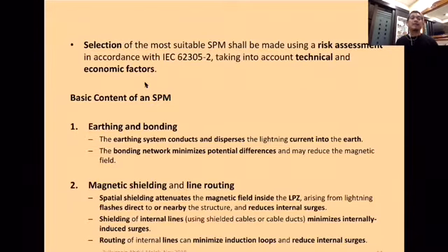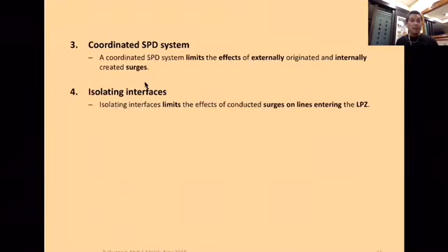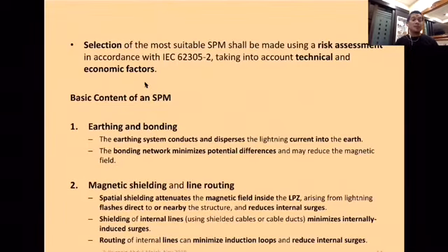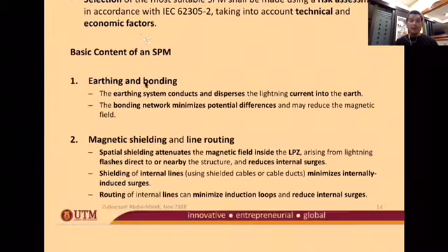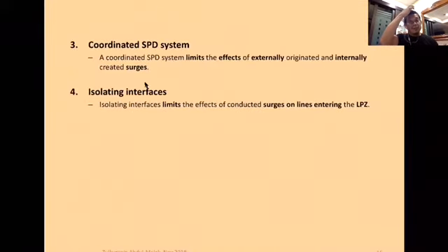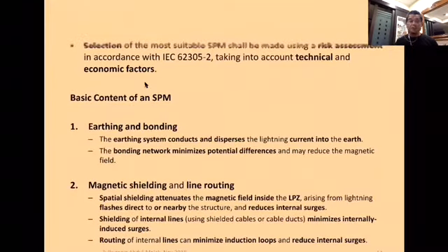So your wiring inside the house before the equipment needs to be shielded, or you can do what we call line routing. And do zoning, and the zoning can be done also using surge protection SPDs, and then you can coordinate between the zones. So we have what we call SPD. You see, previously we have shielding, but if you don't need shielding, because, for example, it's already EMC free, you just need the earthing and bonding, and the next one, zoning by SPD. But if you need the shielding, then you need the shielding as well, zoning by shielding.